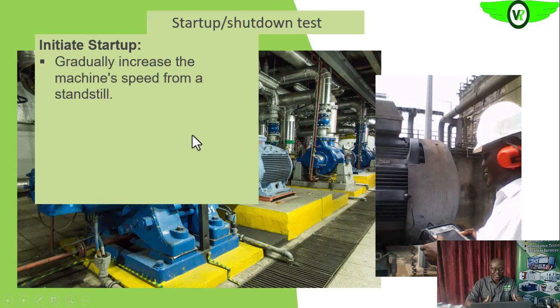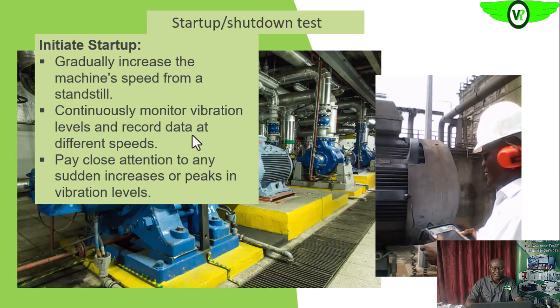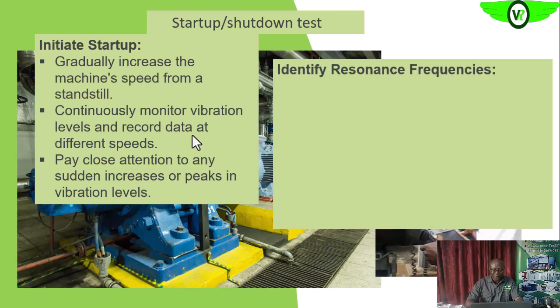But as you are doing that, you are collecting the vibration information from the machine and recording the information that you are gathering. Then you need to pay very close attention to any sudden peak or rise in vibration levels as the equipment is starting up. Look if it is narrow band and if the phase is erratic also.